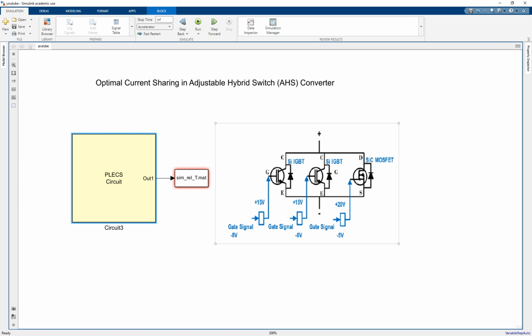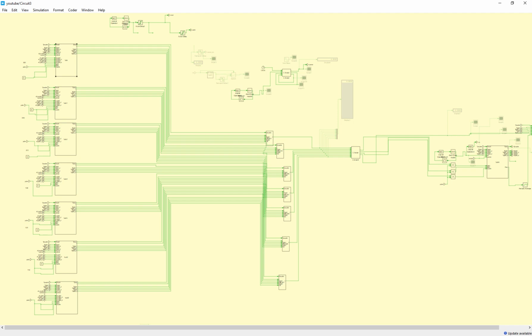Because as I said, from power loss to the junction temperature is a simple linear system, a combination of several linear first order systems. Depending on if you're using the Foster or Cauer model, you can do all of these things in linear state space. I'm going to show that in a few minutes. So that's the reason I do the calculation in Simulink, to speed up and also to have a robust record of data. Okay, let's jump into the simulation.